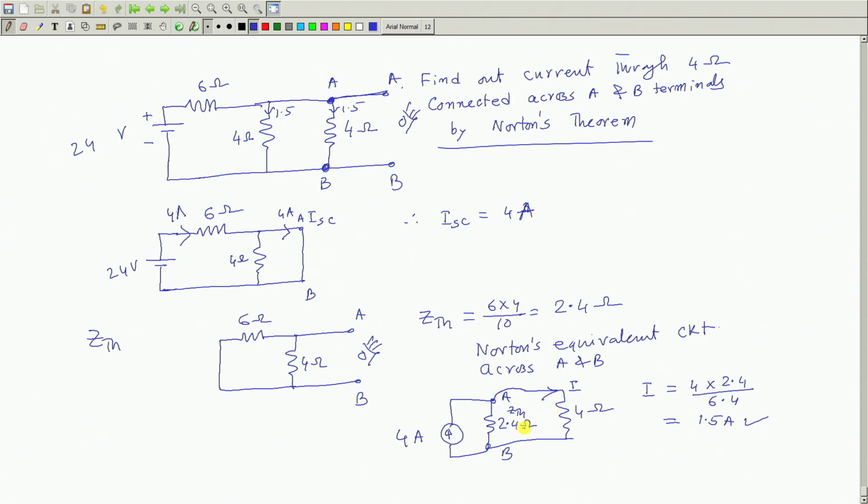We call it Z Thevenins, and then your A B terminal. So, complexity of the left hand side goes. Therefore, it will be very useful if you are interested to find out current in a particular branch. For example, if I say apply Thevenin's theorem to find out currents here, here, here in all these impedances, then each time you have to find out Thevenin's equivalent across those 2 points, that is not a very good idea.